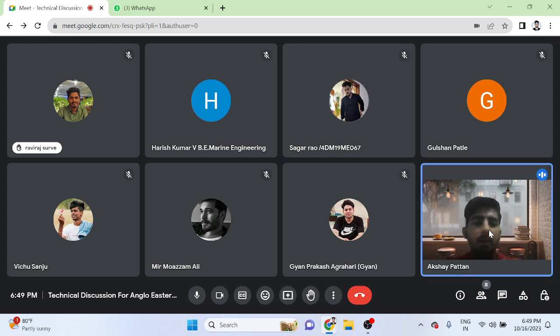I will do. So basically, a gear pump is a positive displacement pump. In a gear pump, there are two gears. One is the driver gear and another is a driven gear. The driver gear rotates and the driven gear also rotates along with the driver gear, as both gears are meshed. I hope you guys know the schematic representation of the gear pump.